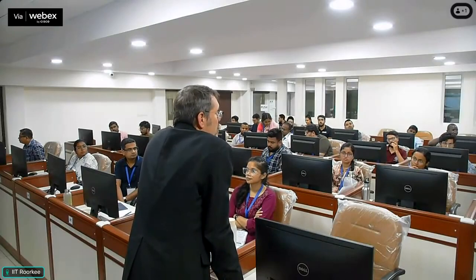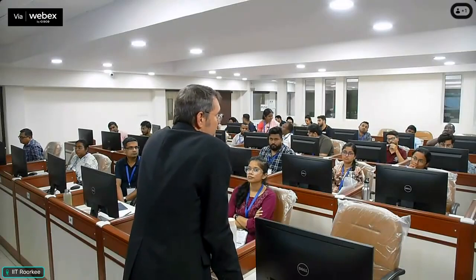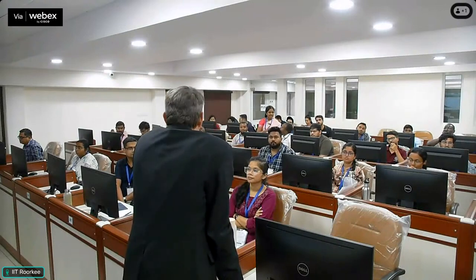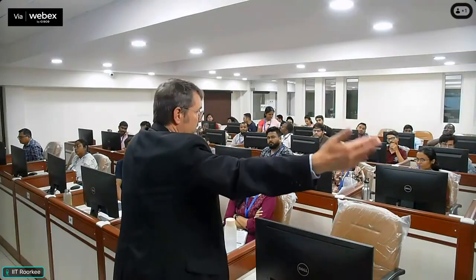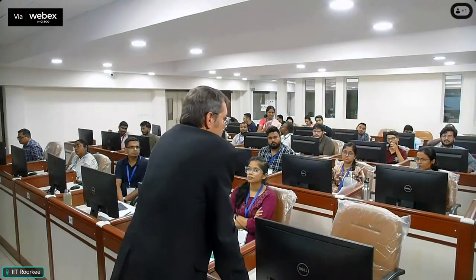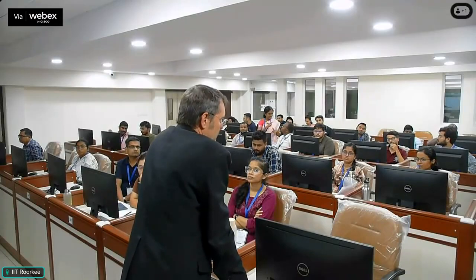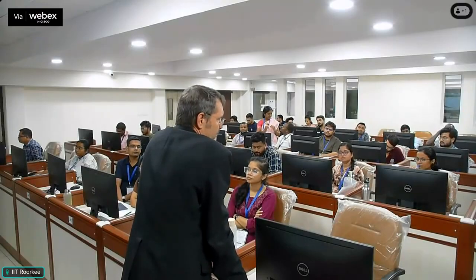80% of the total rainfall. Over the course of a decade, if you continued to capture 35 millimeters, 80 percent of the runoff associated with 35 millimeters of rain in a highly impervious catchment, you would capture roughly 90% of the pollutant load, but if I capture only 17, it is about 60% of the rainfall.